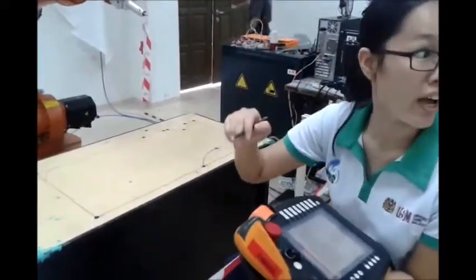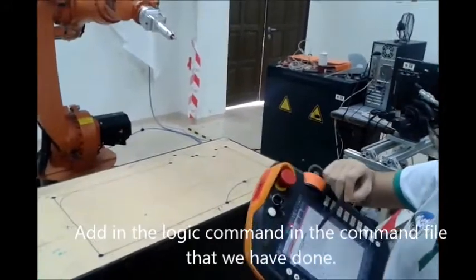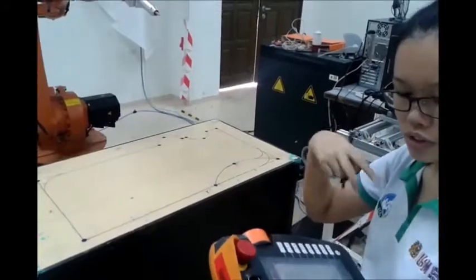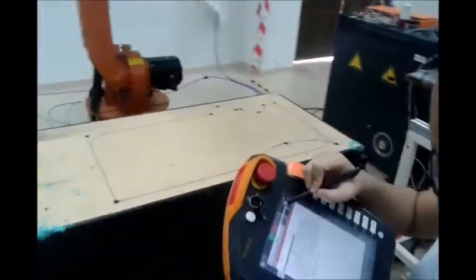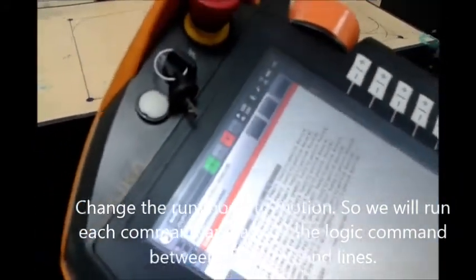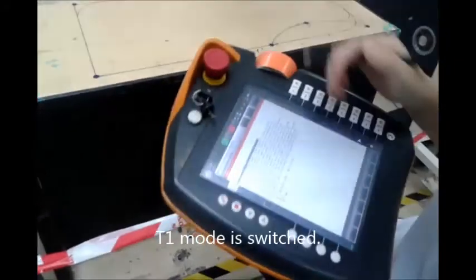So now we would like to add the logic command into the command that we have keyed in this controller. So I will show how to add in the wait and wait for logic command. So before we begin, we would like to choose the program run mode to motion so that we can see each motion by motion, and then we add in the logic command in between. So now we run it.